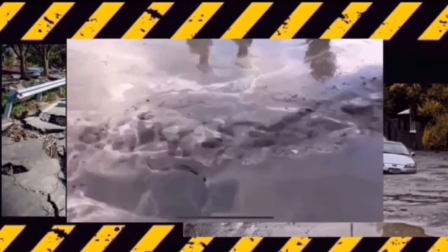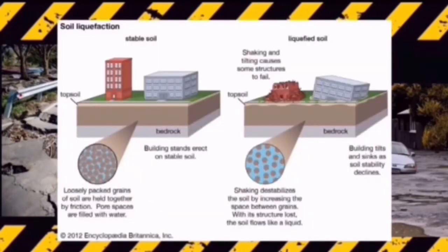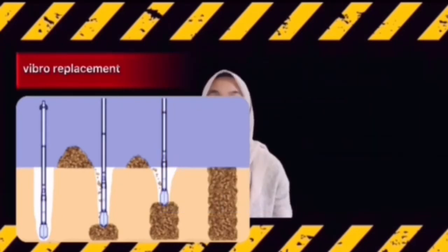Infrequently encountered issues. The first infrequently encountered issue in ground improvement is liquefaction. Liquefaction occurs when a saturated or partially saturated soil substantially loses strength and stiffness in response to an applied stress such as shaking during an earthquake. Vibro replacement is one of the methods of reducing liquefaction potential because it performs vibrations. They increase the compactness of the soil foundation.